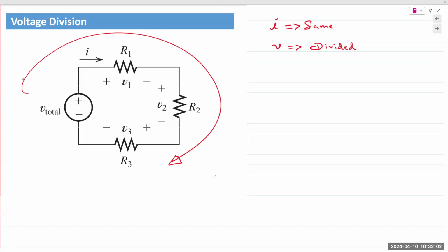So the voltage division principle states that when you apply a voltage to a series network of resistors, a fraction of the supply voltage appears across each resistor. And the fraction is given by the ratio of the resistor to Req. Quite a sentence, but mathematically it's rather straightforward.